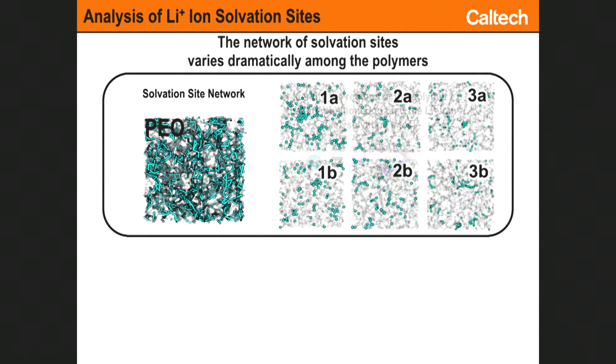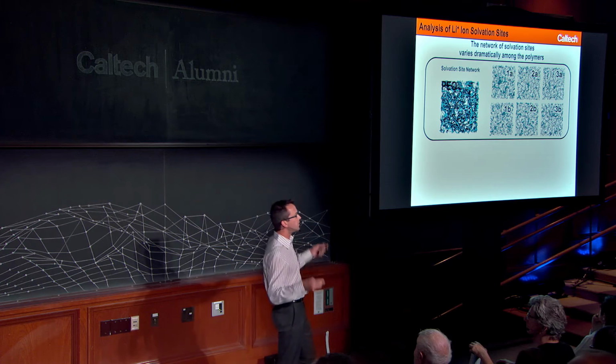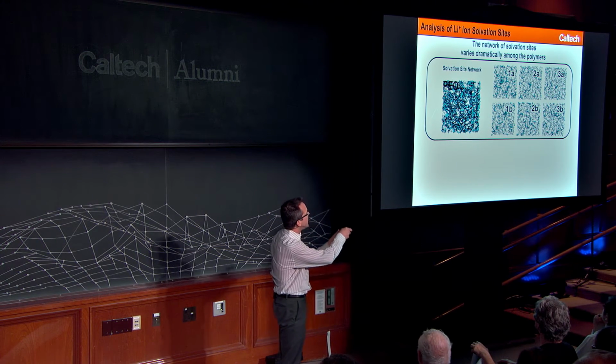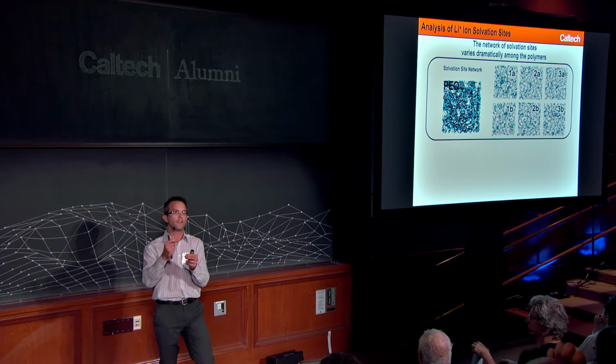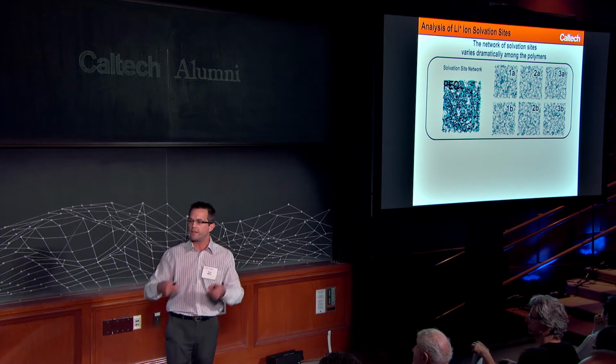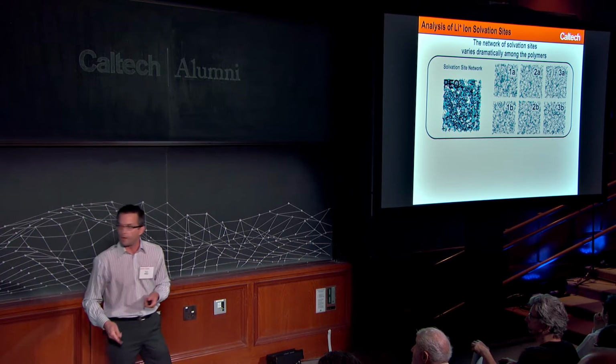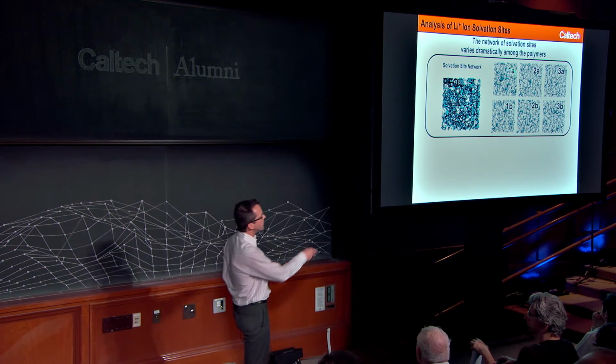And then we did that for all of these other polymers. And the difference was truly striking. Even though these polymers, from a simple molecular perspective, had nothing outstanding or nothing so substantially different than PEO, we saw that PEO intrinsically had these rich networks of places that the ions could live and highways through which the ions could shuttle along to create rapid diffusion through these different polymers.